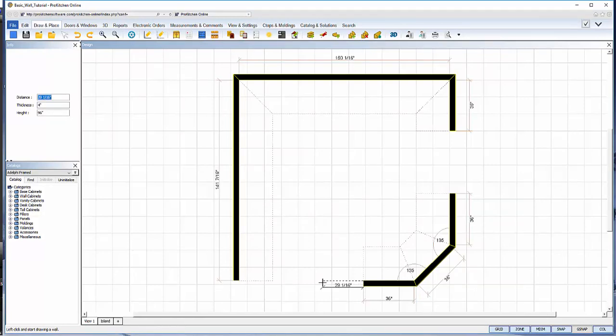So again, I'll click on my sketch tool and use the measuring tool to measure out the 36-inch doorway. Then start my wall. Point it in the right direction, and this time I'm going to draw the wall to my B wall. The walls join. I can tell this because the joint shows in the corner. My walls are set in groups by the way that I draw them. This is important if I want to keep everything together, if I need to move or rotate the whole room.